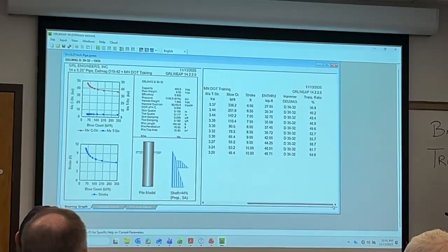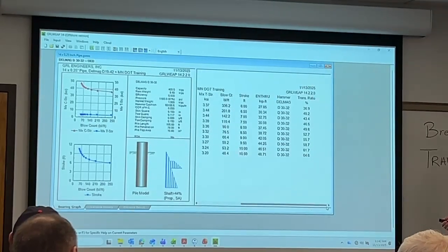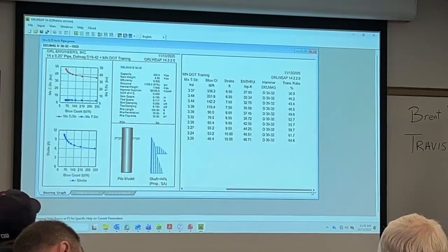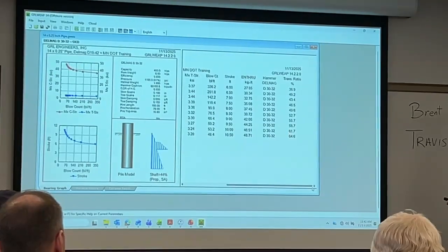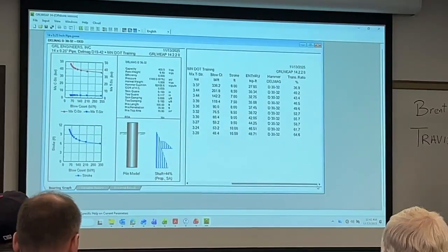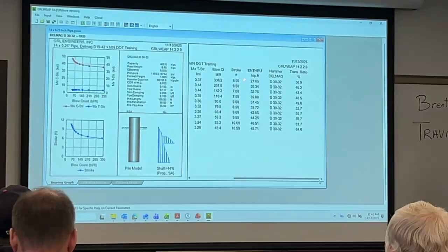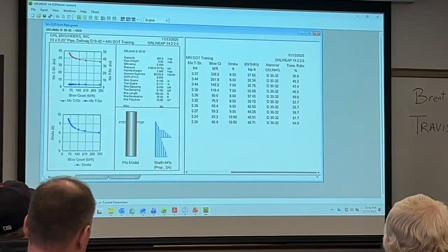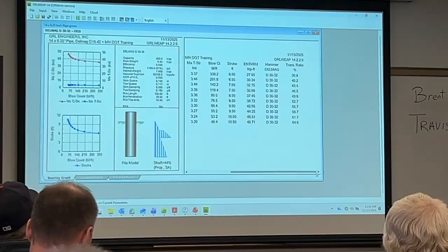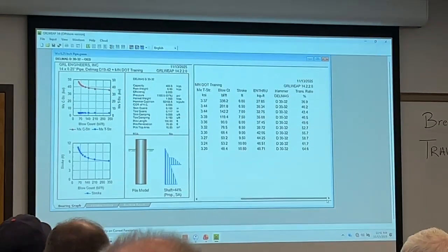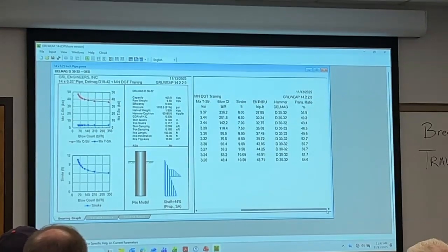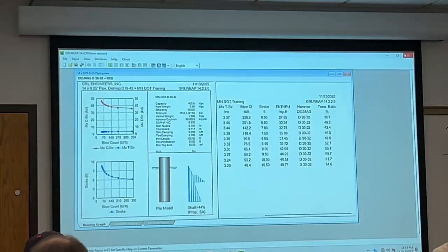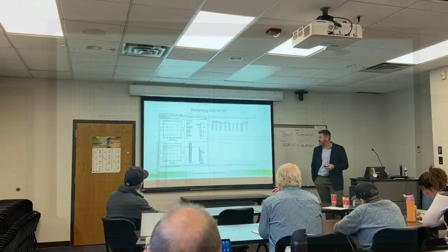So this is fairly, what I said is almost true. So at your maximum strokes, this is predicted with default energy efficiency reductions that transfer 65% of the rated energy of the hammer. When it's down here at 6 foot stroke, 37% of the hammer. So that was showing how we would select a hammer for a given soil or a pile type and pile capacity. Outputs available within WEAP.